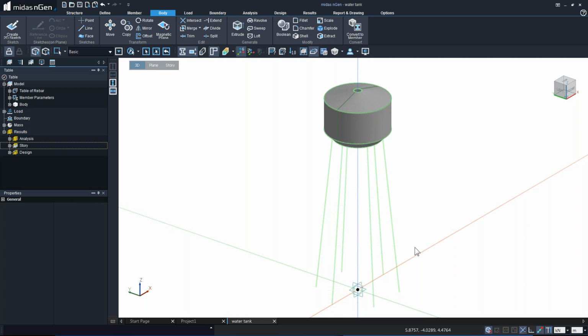Next comes the part of creating beams. So we can create those horizontal lines using this line type of body. Here we can see that the program is automatically snapping on the 1/3 location of our column. So I'm going to be using that snapping and creating these beams. I'm going in and out of the command using the escape button.